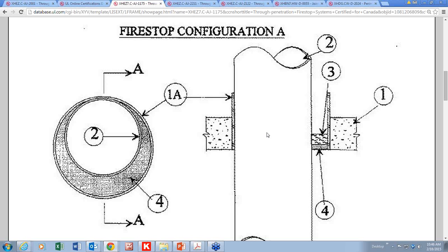Every product data sheet or manufacturer's installation instruction sheet says to smooth or tool the Firestop sealant. If you look at this Firestop sealant, it's smooth. It doesn't look like spaghetti, as can happen when somebody pumps sealant out of a tube. It's been smoothed with a tool of some kind. A professional will use a spatula tool, specifically manufactured by many of the manufacturer members like Albion, who's an FCIA member tool manufacturer, to make a smooth surface.